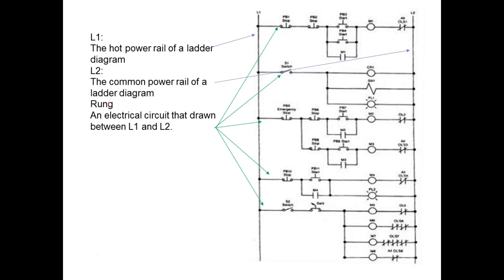But on the other side, it's called L1 and L2 too. So when you get into real diagrams, they might call this PL1 and PL2, or they might give it another name. Usually they put L1 in there somewhere, but they'll give it another name besides L1 and L2 because that's what we call the three-phase lines. Three-phase line over here, we call this L1, L2, and L3. And this happens in motor control.